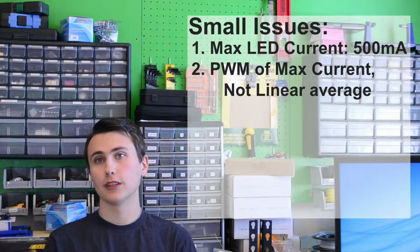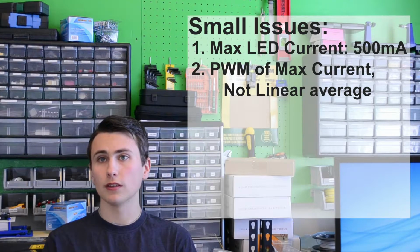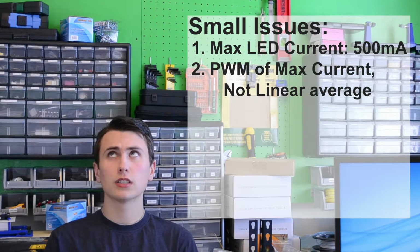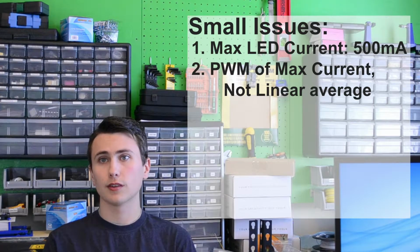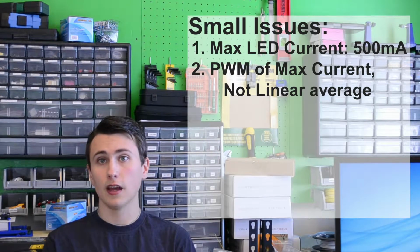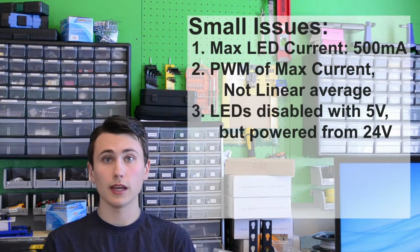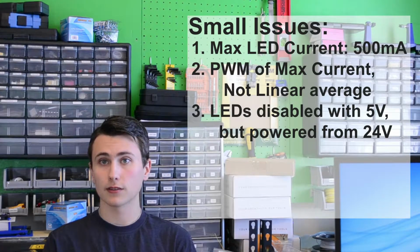Since the microcontroller is regulating the RMS power to a maximum of 300 milliamps, this wasn't a huge deal, and I didn't notice any issues from the 500 milliamp set point for a few weeks, in fact, which leads to the bigger issue. In the first iteration of the design, the current regulators were fed by the 24 volt input at the barrel jack, and were disabled by transistors that were enabled by the 5 volt rail. So that is, the 5 volt rail biased a transistor, which turns off the current regulators. That's still the topology of the design now.